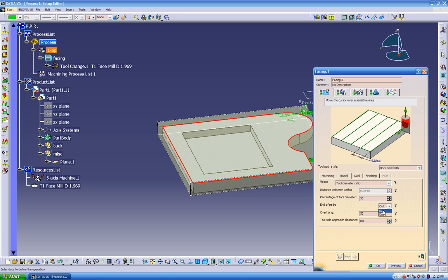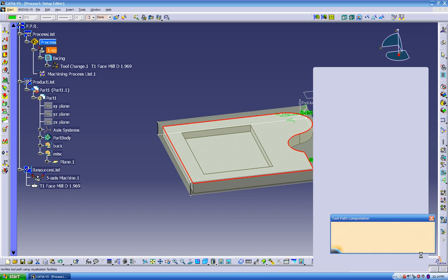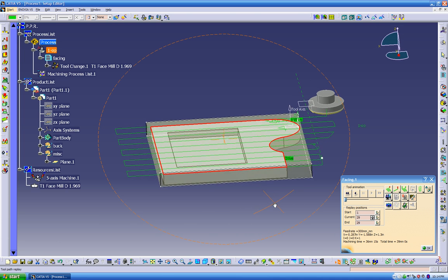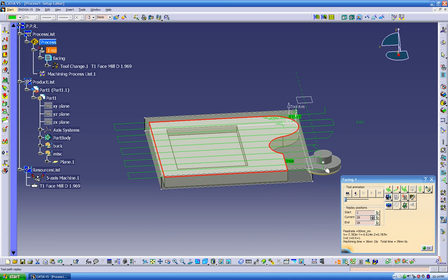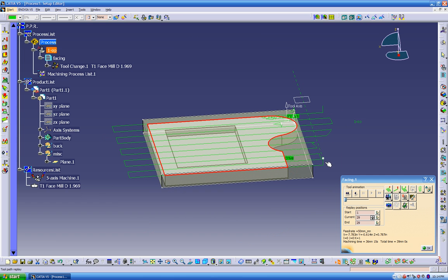So we turn this option on. Make sure the tool goes on the outside of the part. Now it's in. Now it's out. And also we can change this over here, the distance. We can put 1 inch just for reference right now. And we can put a replay. And the tool is being offset to 1 inch from the edge of the part all the way over here. And see right now we're plunging a little bit more on the outside.